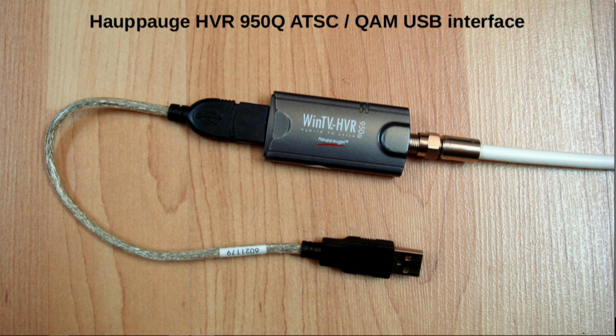For cable, there's a variety of different adapters that support the QAM256 demodulation. I use this USB HVR 950Q tuner. But tuning the out-of-band channel is generally not supported by these interfaces. In a cable box, it's handled within their integrated chipset, and for the clear QAM these devices are marketed for, access to the out-of-band isn't required, so they don't put that tuner inside.